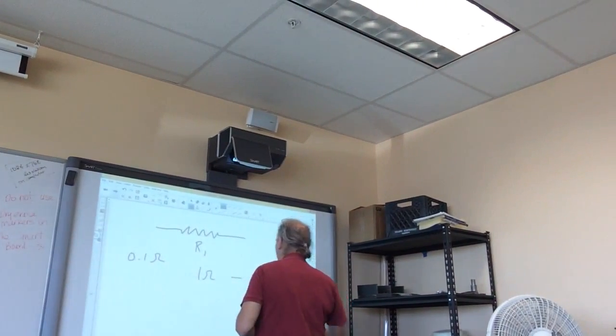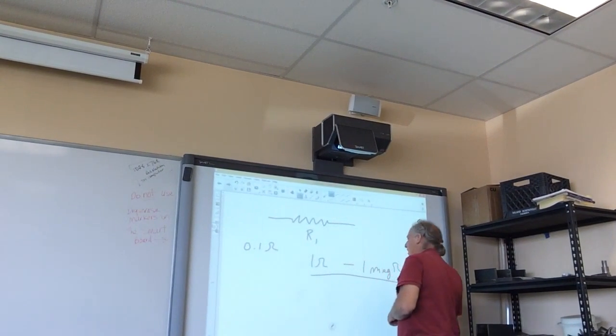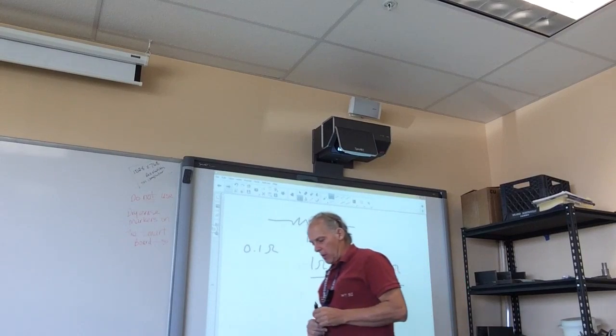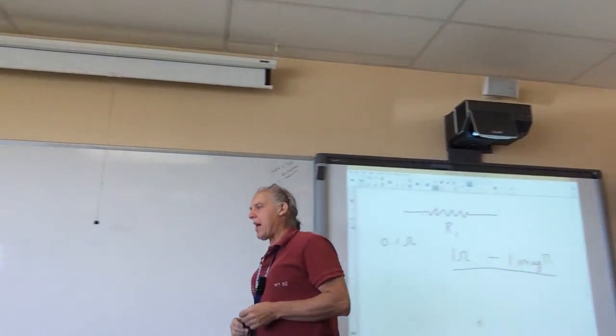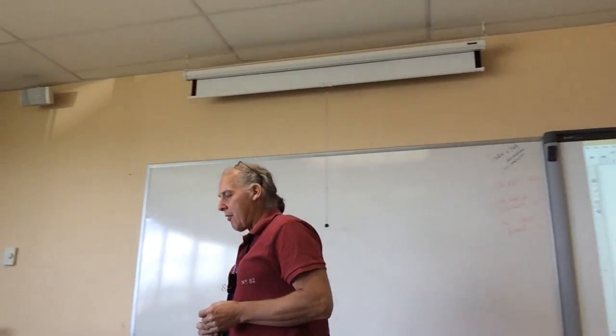All right, so we will probably see resistors in this range. 1 ohm, pretty close to a wire. Meg ohm, pretty close to an insulator. 1 ohm you'll probably see in high watt, because if there's any current, you've got to have a pretty high wattage resistor to be able to stand the current if it's at 1 ohm.